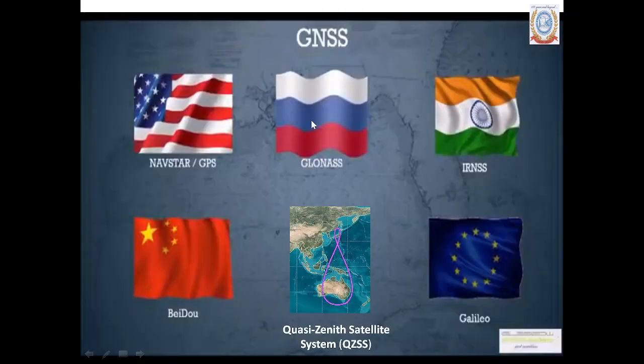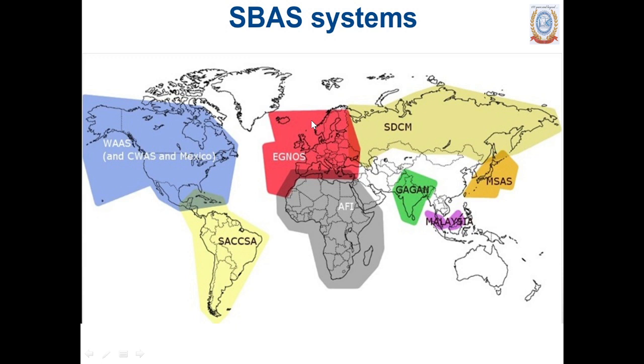Even for land surveys, it can go further down using an RTK GPS, real-time kinematic. It's not our interest of discussion today, but that itself is an area where you are required to install a benchmark, referencing, etc. These RTK technologies are going to give you an accuracy of even millimeters. Okay. So these are all some augmentation satellites.